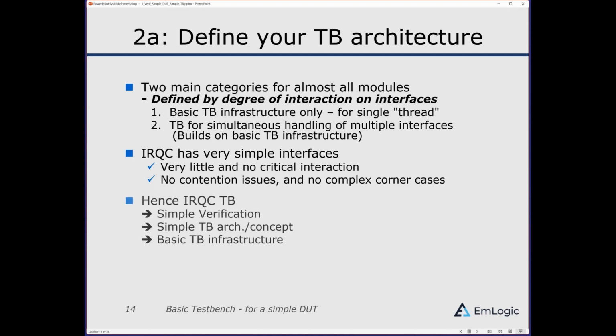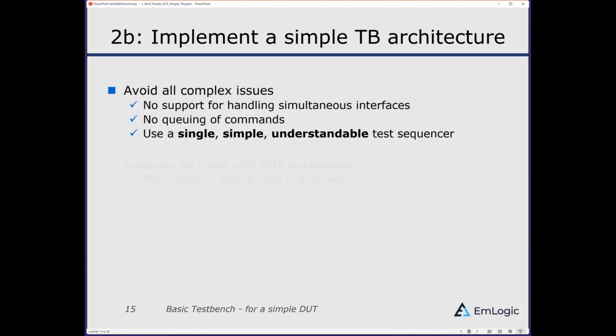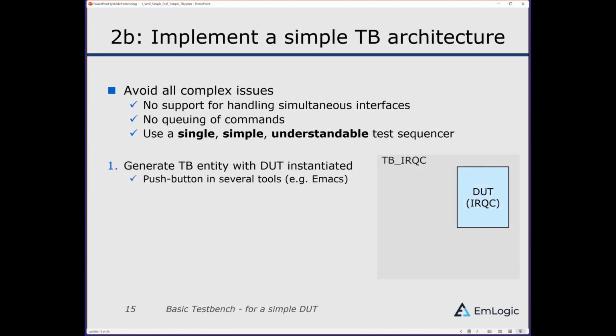Next step up is to define your test bench architecture. And in my opinion, there are two main categories for almost all modules, and that's, in my head, defined by the degree of interaction on interfaces. So the simple case is a basic test bench infrastructure only, or something that could be handled with everything controlled from a single thread.